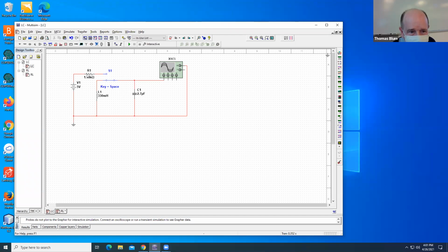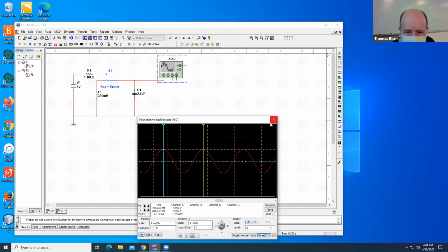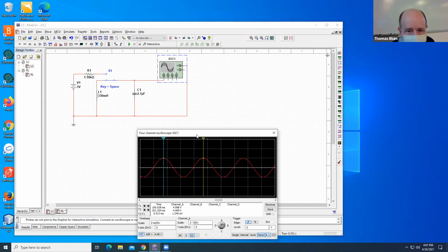So the resistor is with the capacitor and the inductor is with the capacitor, but never all three are in the circuit at once. So what's going to happen is first it's going to be flat, and then I'm going to flip the switch and it's going to be a charging capacitor. We know what that looks like. That's that sort of hump going up and saturating. And then we're going to close the switch and it's going to do what you see here, this sort of oscillating effect.